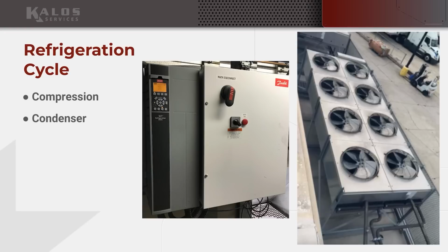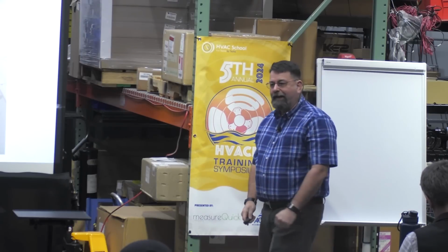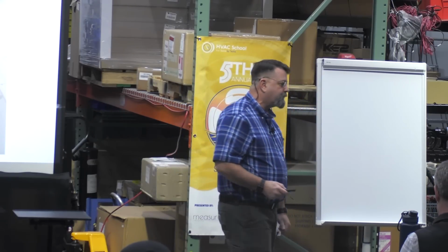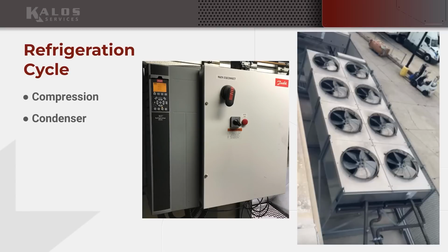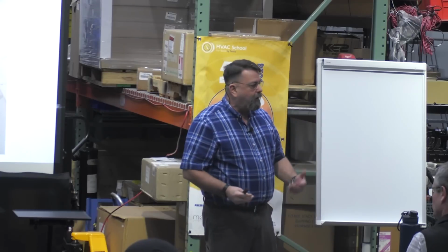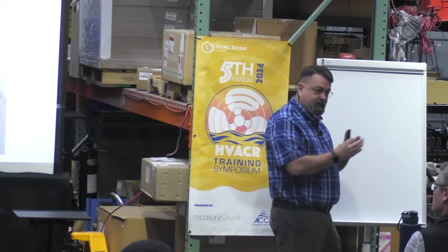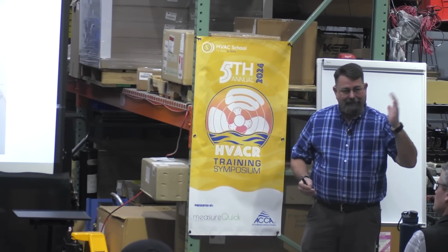Another is let's keep all of our fans on and just slow them all down, okay? That's the more modern version. This is what we're seeing with newer construction. This particular one was a retrofit that was done probably 10 or 15 years ago. That's also fairly common. That's a VFD, variable frequency drive, that can do that, right? Another is EC motors. I can send it the 0 to 10 volt signal that tells it where to run.